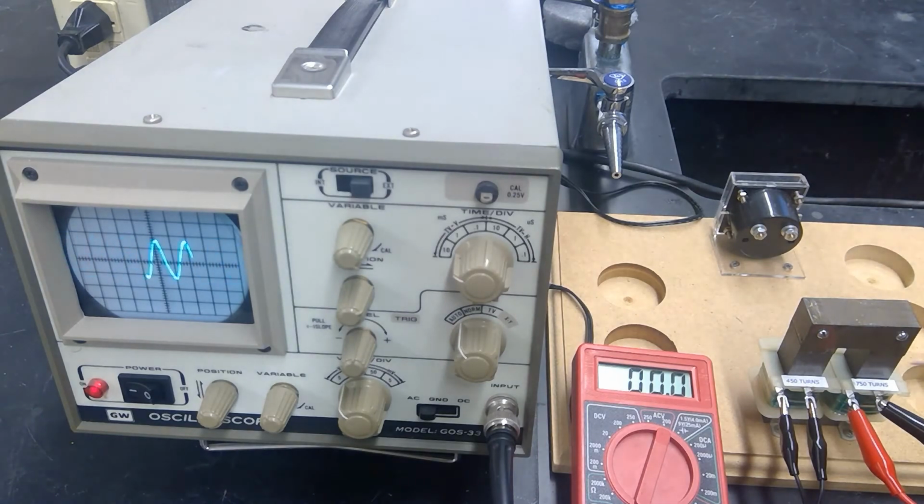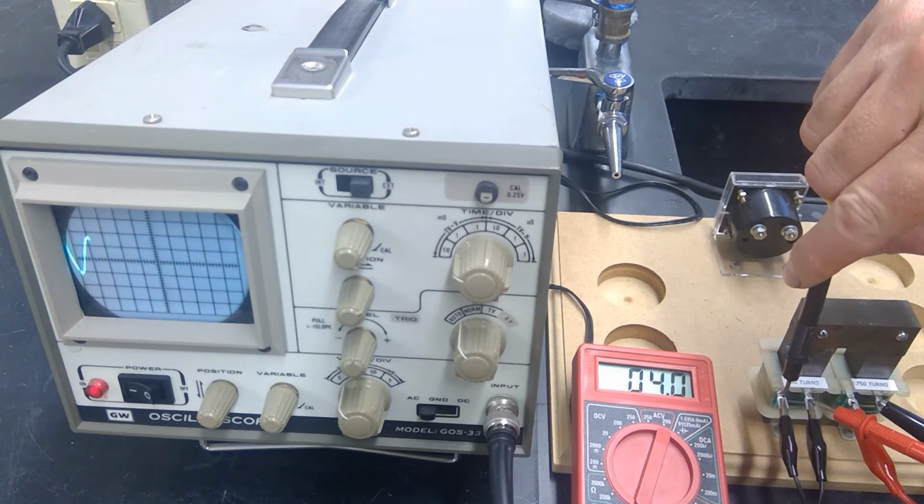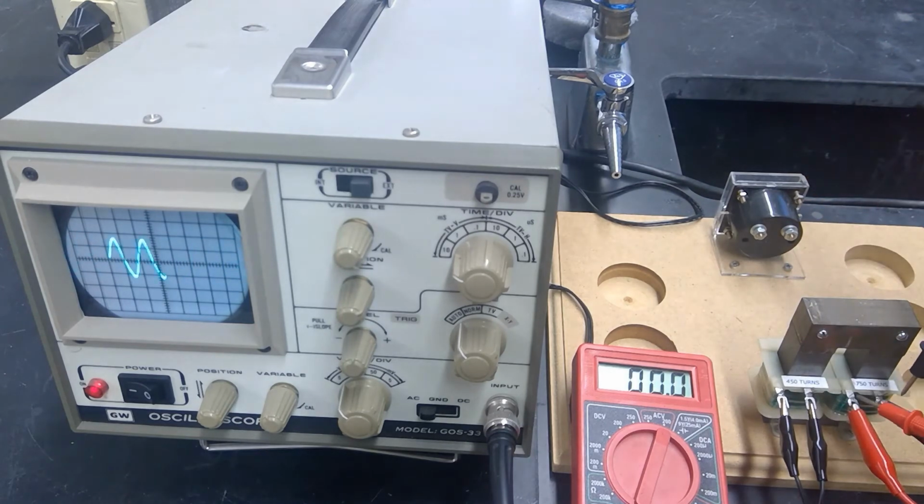So we are going to get some losses. This is a very cheap design. Also note that these wires are kind of loose because they're meant to be able to be moved and changed around. So that's going to account for some of the loss. But as you can see, we have an increase in voltage from the initial 5.8, 5.9, and we've stepped up the voltage to about 9.6, which is close to our predicted ratio of increase based on the ratio of secondary turns of the transformer wires to the primary turns.